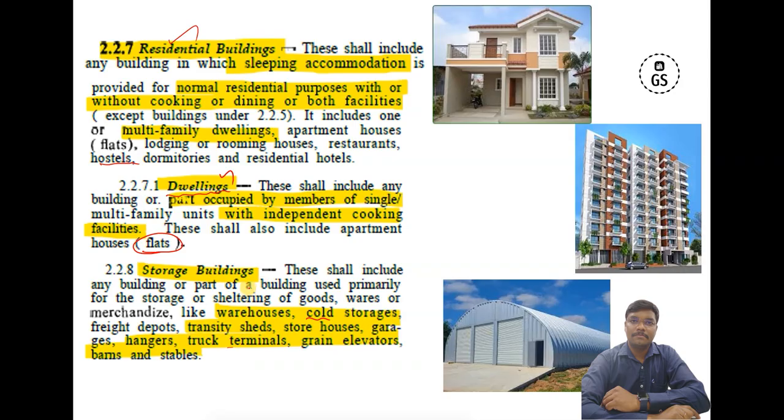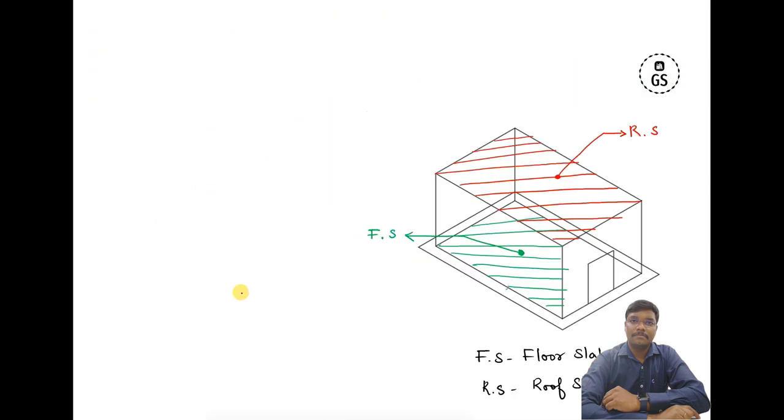So when you come to the conclusion of this part, when you calculate the structure, we need to know the dead load plus live load. Both combinations are required. We generally take a factor of safety, that is, a multiplication factor. We go for a factor of safety of 1.5 times dead load plus live load for basic considerations.